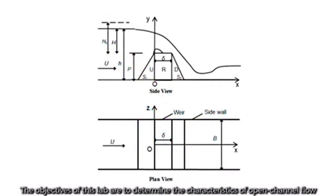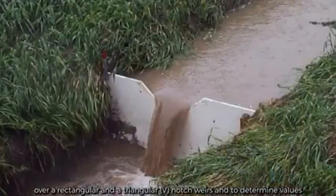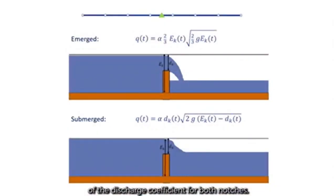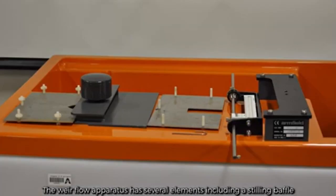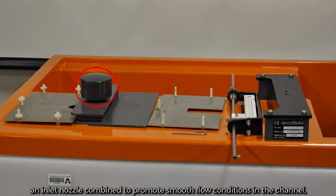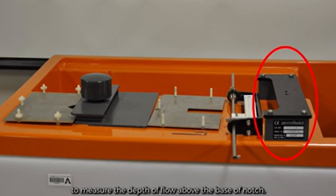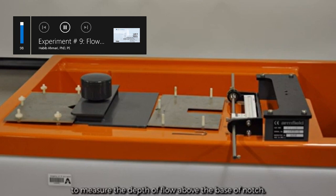The objectives of this lab are to determine the characteristics of open channel flow over rectangular and triangular notch weirs, and to determine the values of discharge coefficient for both notches. The weir flow apparatus has several elements, including a stilling baffle, an inlet nozzle combined to promote smooth flow conditions in the channel, a vernier hook and point gauge, all mounted on an instrument carrier. These instruments measure the depth of flow above the base of the notch.